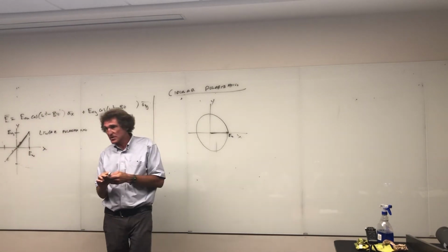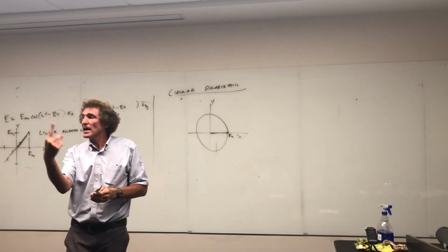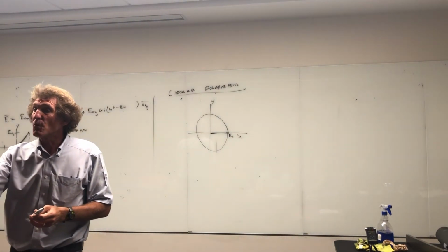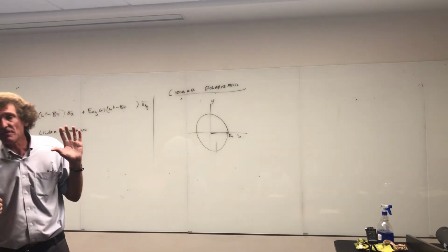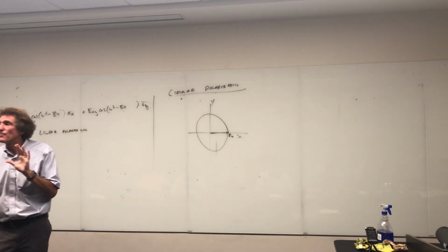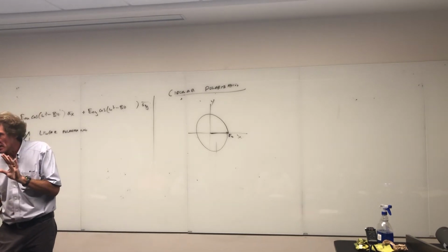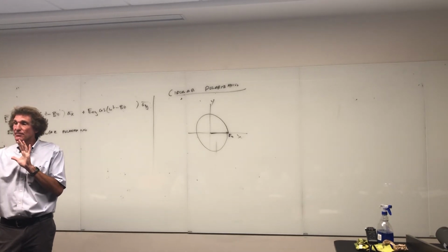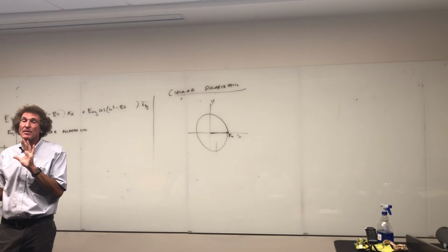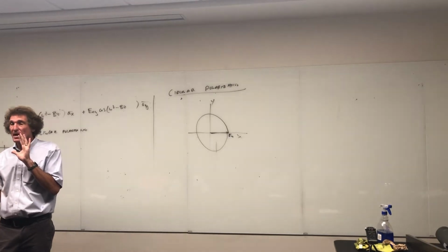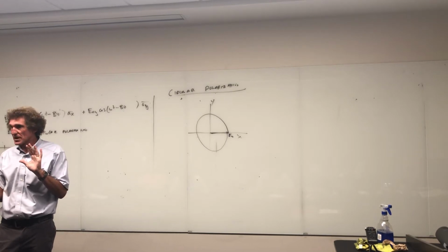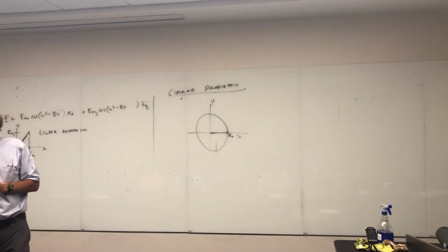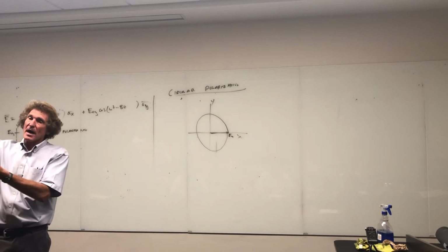But there's one other thing about this that's important. With circular polarization, if I send down a right-hand circular polarized wave and it hits the wall, it comes back rotating the other way, which means at the receiving end, I can build an antenna that will filter out everything but the polarization I would get from a return. And it's very, very nice for radar work to use circular polarization, and the weather people will actually use elliptical polarization